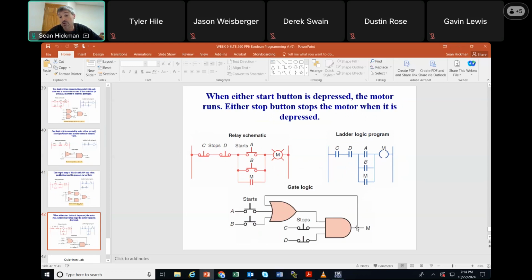So on some Boolean, you can just draw that around like this and then feed it right back into itself, because the output is an input. So here they're taking the output and wrapping it around as an input. On Siemens, you can't do this. On Siemens, you just put the address right there. It won't wrap around. You just take the output and put it in there as an input, and then it would work. So if you have a memory situation like that, you don't draw the line. You just put that value in there.